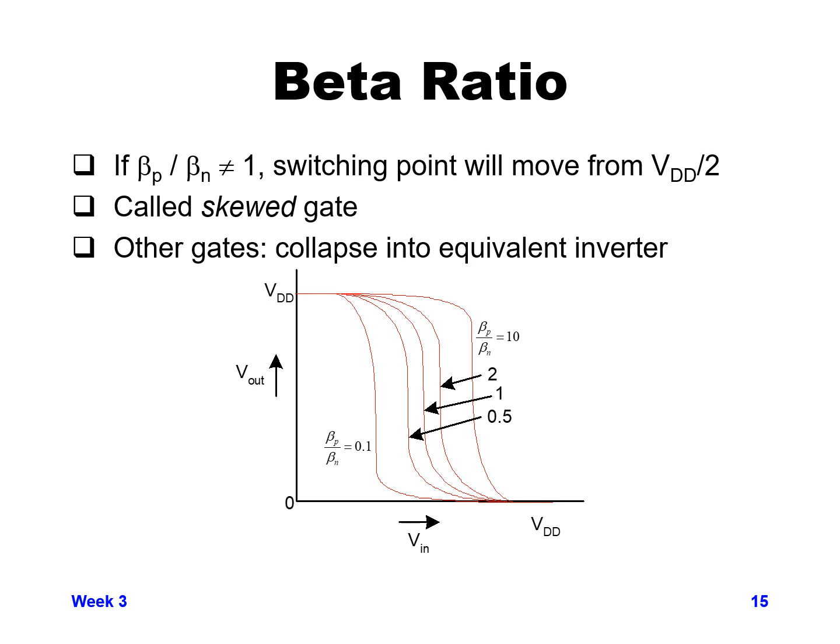Your inverter is going to switch output voltage between 0 and 1 as input voltage switches between 0 and 1. When they both get to the 50% point is where that steep part of the curve is. So 50% of VDD for the input is going to cause 50% of VDD for the output, and it's going to switch really quickly. Small change in Vin is going to cause a very large change in Vout right at that 50% point.